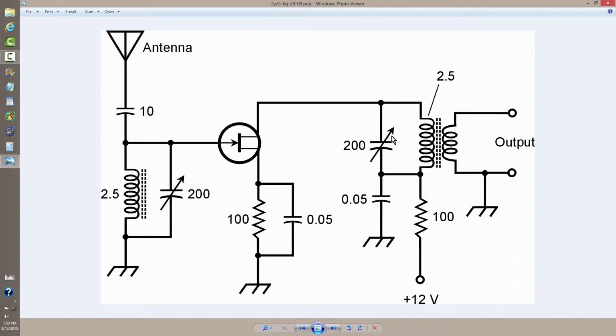So whatever the resonant frequency I chose for this circuit is, it's probably either 7 or 10 megahertz. I chose 100 picofarads for the capacitance, which would be about in the middle of the range of this variable capacitor and this one, and then calculated the inductance that I would need and designed the circuit on that basis. Then, of course, this being a variable capacitor and this being a variable capacitor, in practice allows for precise adjustment of resonance. But the formula is useful for getting a ballpark idea of what these component values ought to be when you design the circuit. So I hope that I've answered that remark, actually the viewer's main question.